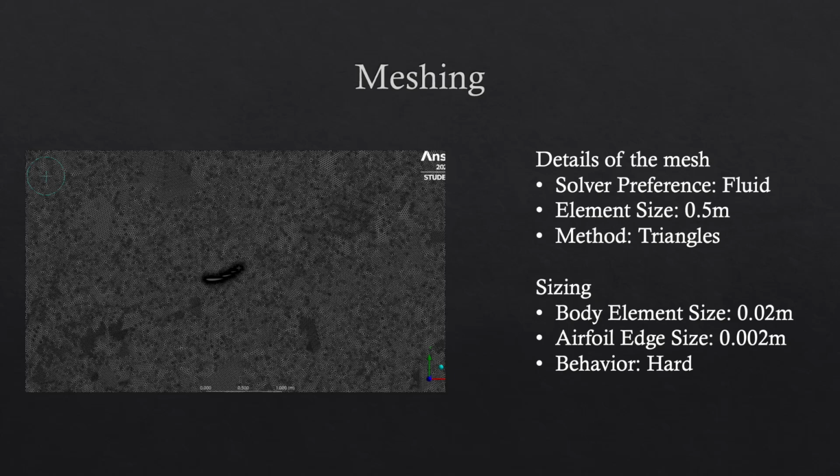The mesh was refined by making the body element size 0.02 meters, along with the airfoil edge size to 0.002 meters. I specified smaller element sizes in these regions to capture the fine details of flow separation and reattachment.